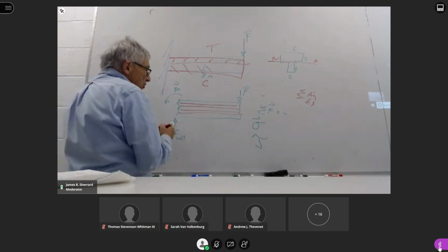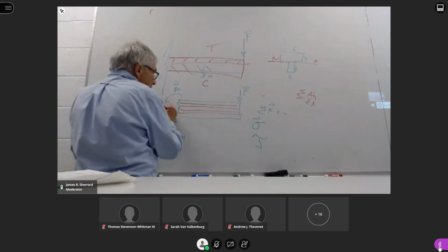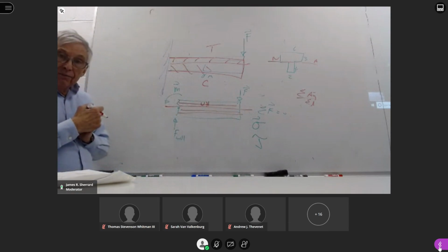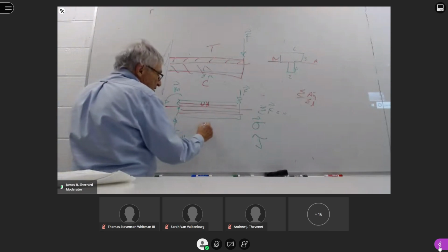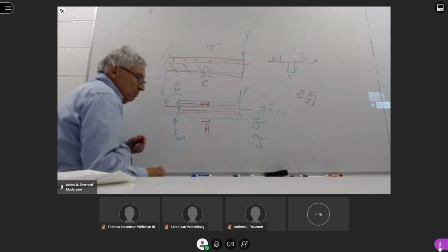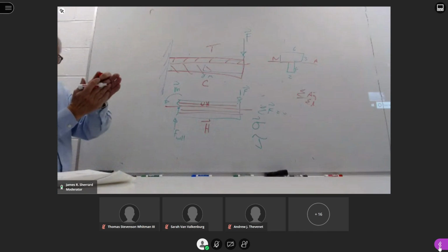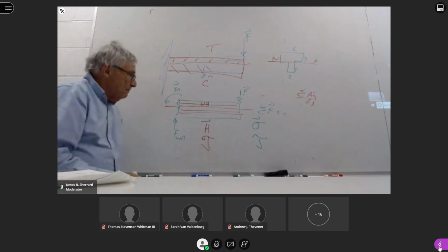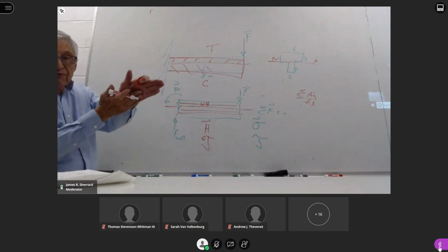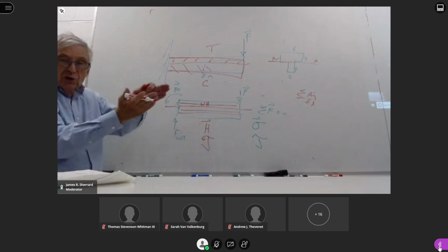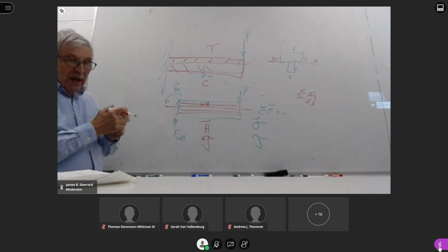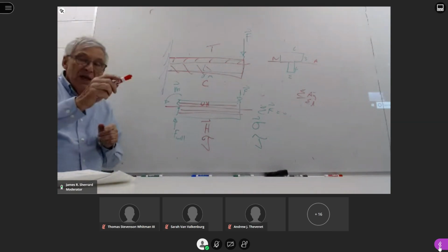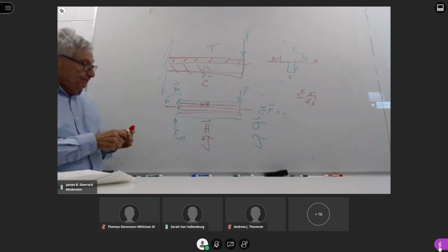And just like we've had a vertical shear here, we could cut this and look at the upper half with a free body diagram. You'll find out that there's actually a horizontal shear. If we divide this by the area it's acting on, we have a shear stress. So we could actually have the system fail due to this horizontal shear, as well as the bending moment where it pulls out from the wall. We're going to start on this after we come back after Thanksgiving.